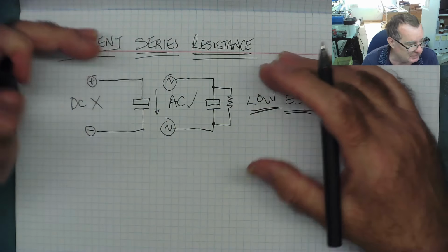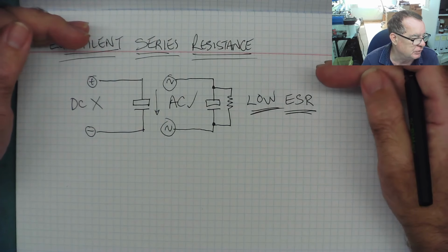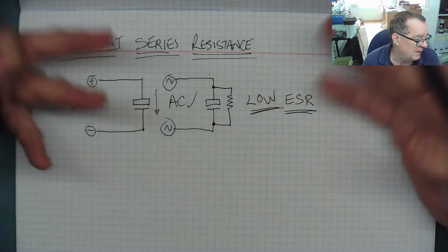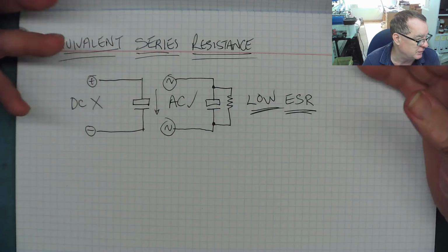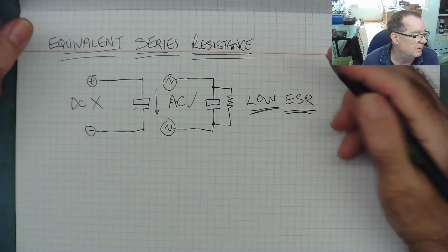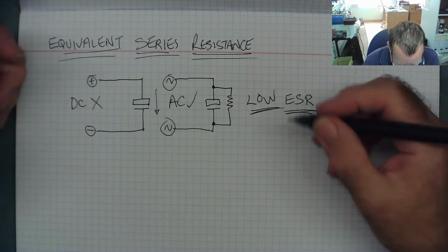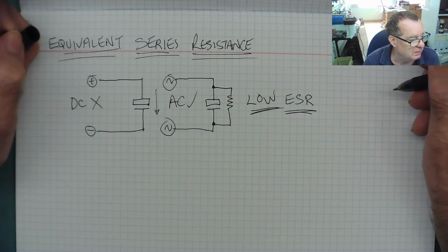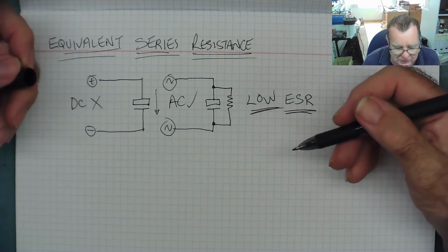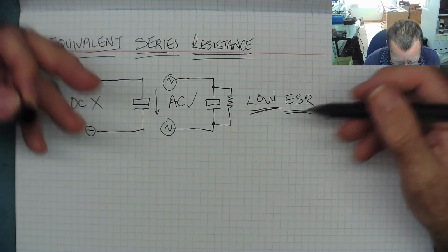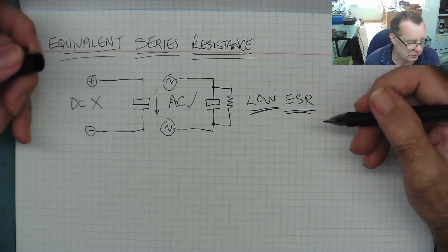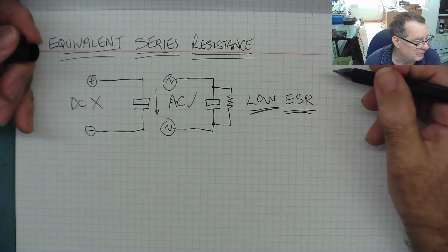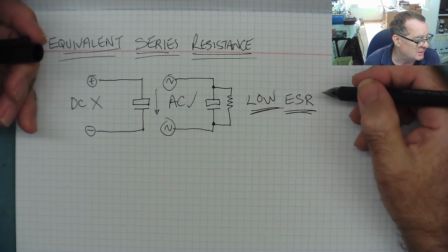If it's badly out of spec, much higher than it was designed to work with, you could blow the MOSFETs that are driving it, or the transistors, so you can actually blow the power supply up because of bad capacitors. This is why it's important to test capacitors for ESR. Not only in switching circuits, in audio amplifier equipment and other applications, it's also an important factor. So let's have a look how we actually measure ESR.